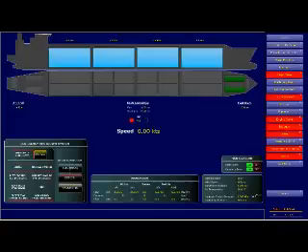And at that stage, we will decide how much heel we want to maintain. Keep that heel. And in the end, you will see that the pumps will automatically trip off if their bearings are not getting LNG for lubrication, because LNG itself is a lubricator there.